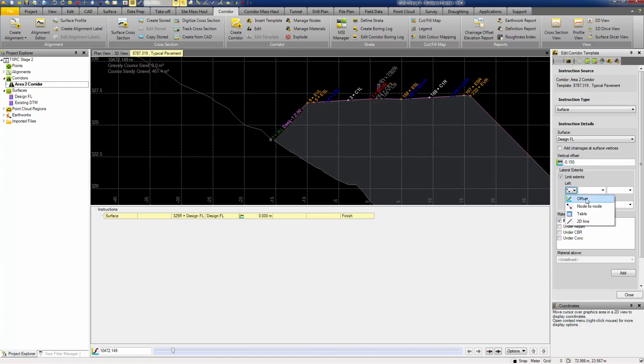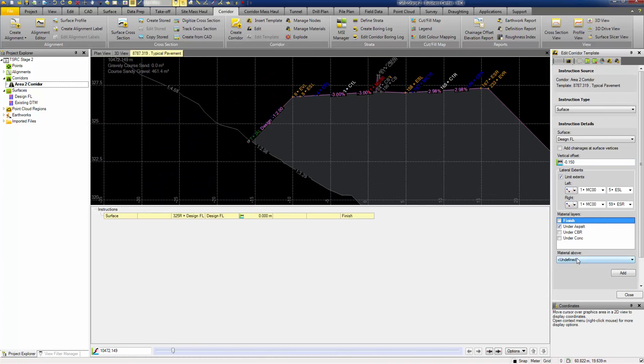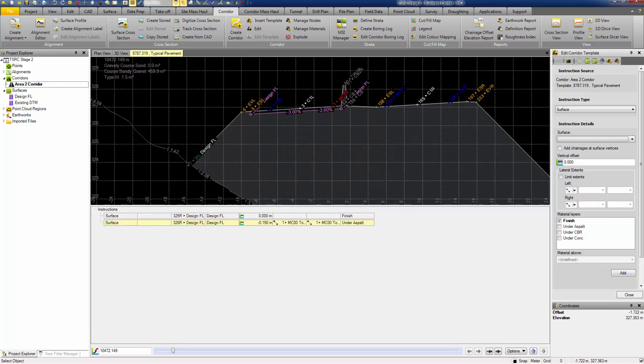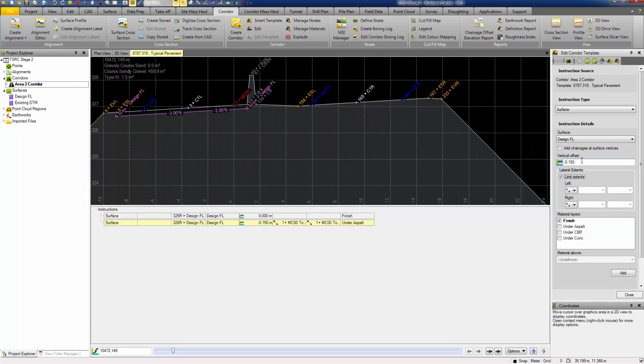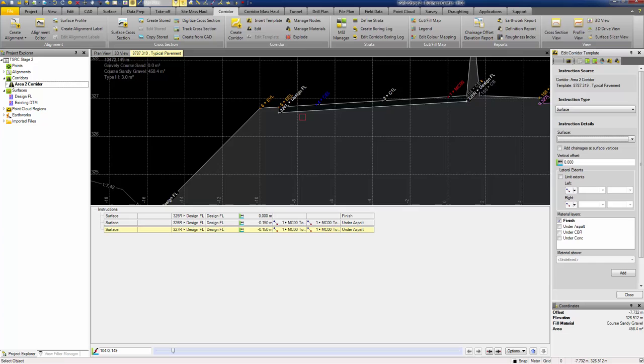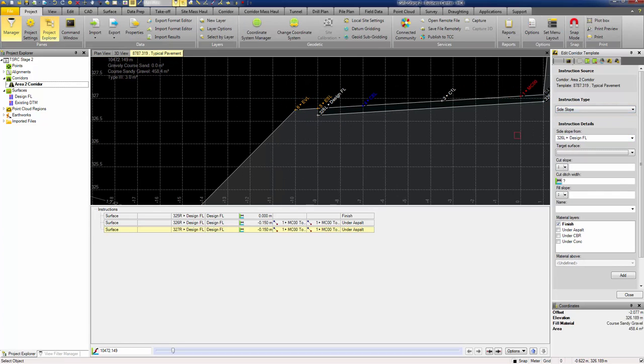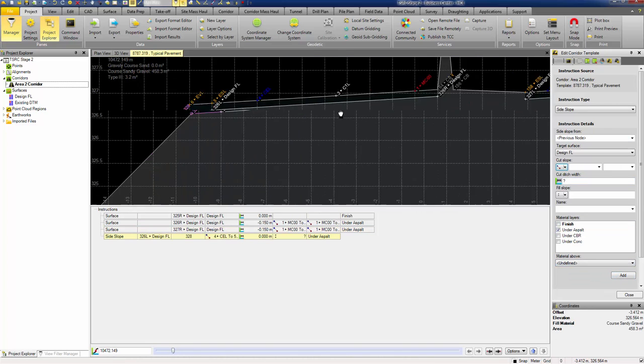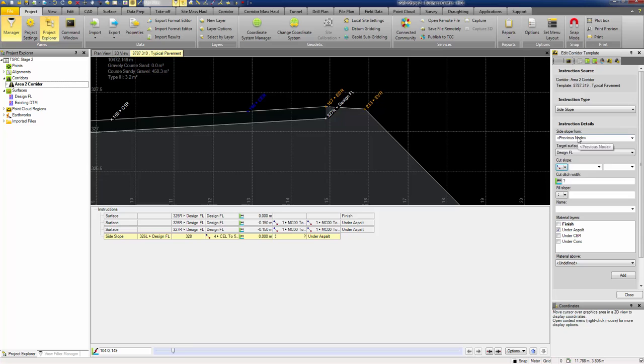And now I'm going to just vertically offset some portions of that design, the pavement sections, to give us the underside of some pavement. Do the same for the other carriageway. Out on the edge we want to project that pavement grade, and we want to have that hit the design batter. So we'll just define that again on the left and right sides, and we'll continue building up this template.